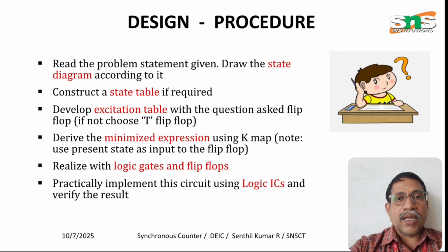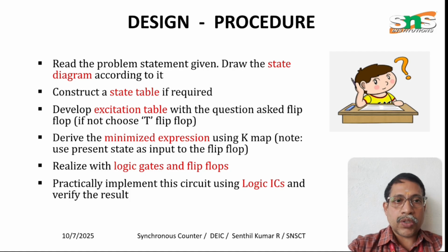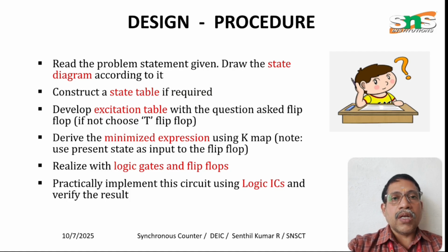For practical implementation, you have to purchase the flip-flop ICs, the logic ICs, a breadboard, and a trainer kit, such that the input is given in terms of clock pulses and 1 and 0 with the help of a toggle switch, and the output is verified with the help of an LED. If the LED glows, it resembles 1, and if it doesn't glow, it resembles 0.